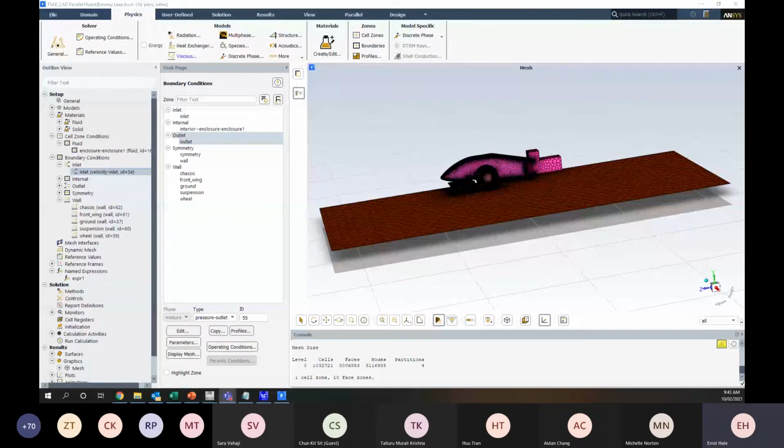Okay, so we're getting to some more detailed questions. In a blood flow simulation, can I give pressure boundary conditions to both my inlet and outlets? That is a case-specific question again, sometimes. Just specifying pressure at inlets and outlets can make for a poorly specified solution, and can make difficulties in terms of solving. So if you have trouble with your convergence, make sure you go to the support hotline, and we can answer questions like that in a bit more detail.